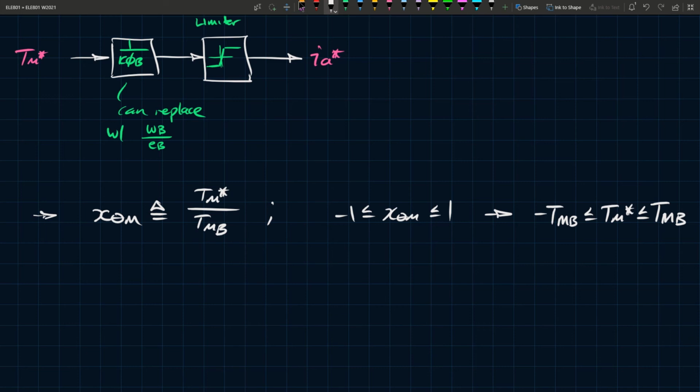So practically speaking, you can imagine that this x theta m is like your acceleration pedal. How much are you demanding from it? Are you demanding it to go all the way to 1, or are you demanding it to be 0? Or I guess negative would be if you switched gears and went into reverse, right? That would be the negative version of x theta m, because there's not a reverse pedal; your pedal can't reverse without changing the gear. So based on this formulation, we can do the following.